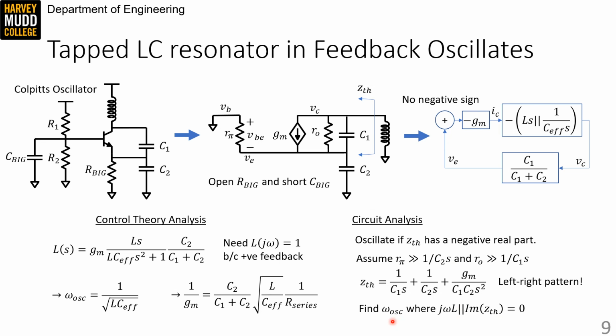As a final note, I want to emphasize how easy these oscillators are to make by accident. For instance, I've seen Colpitts oscillators where C2 is a bypass cap, like a CE, in order to build an amplifier, and C1 is a breadboard parasitic, and this inductor is just a long wire to the power supply. So watch out, use careful circuit construction techniques to avoid making these.